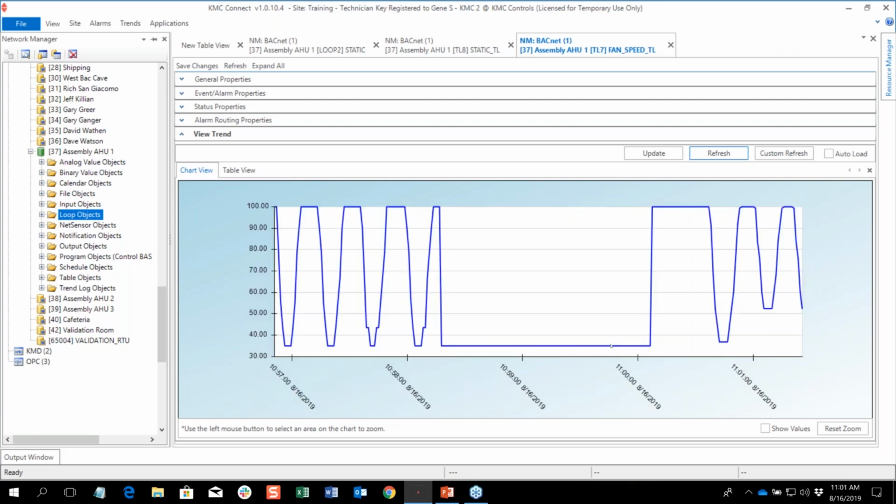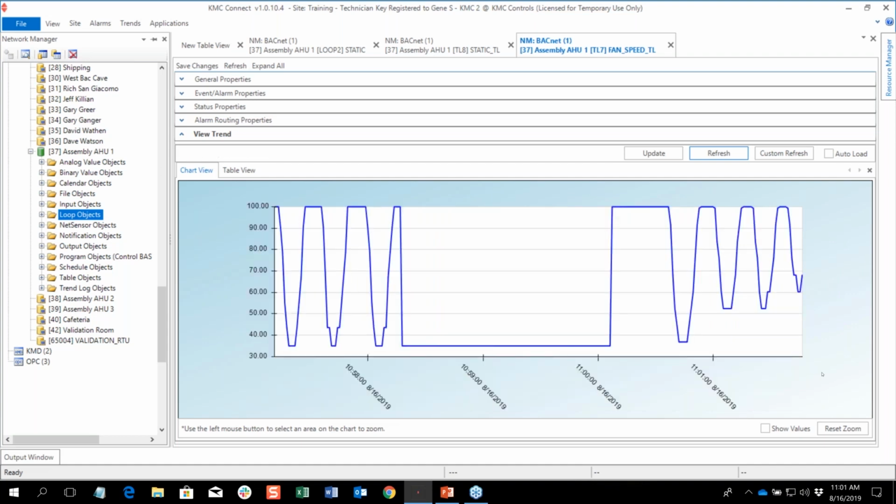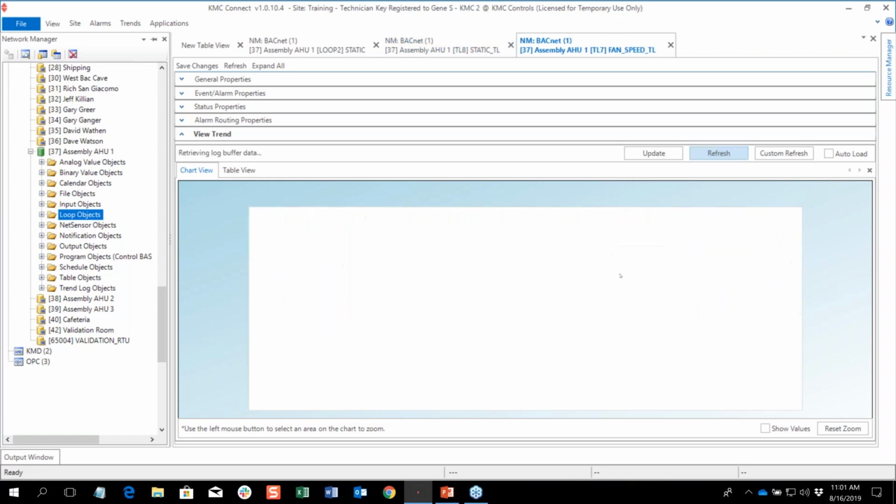So as you can see, that's already the oscillation compared to what's way on the left side when we had 0.05 compared to 0.075. We can see a little bit of a difference already in the fan oscillation. So the frequency of oscillation may be the same, but the amplitude of that oscillation is really what we're looking to manipulate here. So since we're not really narrowing in on a value, is it time to adjust that proportional constant again? Yeah, I was just going to give it a little bit of time to see where it's going to, the oscillation was still getting smaller.